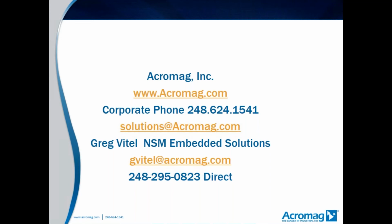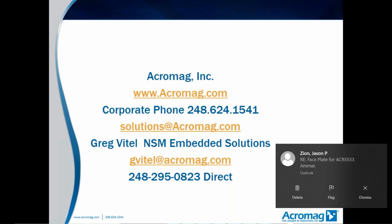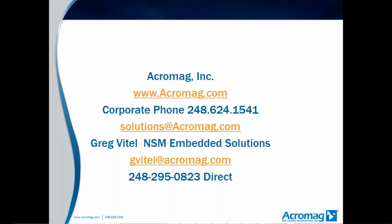Okay, very good. Another one came in here. Can you explain the difference again between FPGA and CPLD? Yeah, so CPLD is complex programmable logic device. It is typically a device that is much smaller in size and much less expensive. PLDs and PALs were around before the CPLD, and they're typically a little bit faster to program. They're non-volatile in most cases, so once you program them, you don't lose the program upon power down, and they're still used quite a bit today. They're not as complex, and you typically will find a lot of CPLDs in applications that are consumer or industrial oriented.